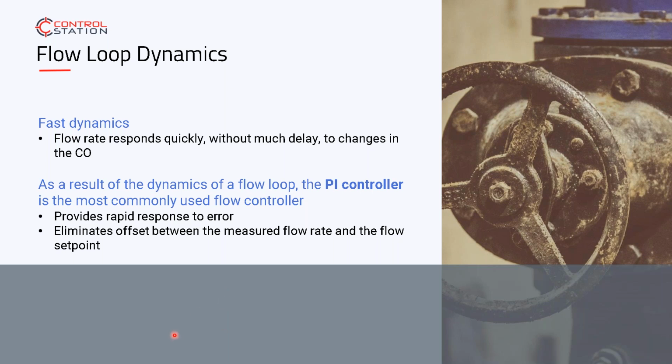In reality, your flow is going to change due to disturbances. But if you overreact to those disturbances, you're just going to push the other bump down the process also. So a respectful change in flow systems will allow your downstream temperatures, etc., to react at their rate of change.